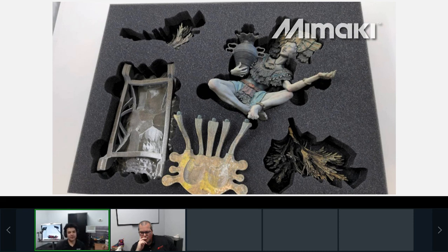It's also very convenient when you need to pack and ship all these parts. The possibility of breaking parts is reduced by separating into components. If you break a component, you only print the part that you broke, or if you need to redo something, it's just one print. That's another big advantage of components. You can always reduce print time as well. It's a very common practice in most industrial processes: try to have components, for convenience and to reduce part rejection.